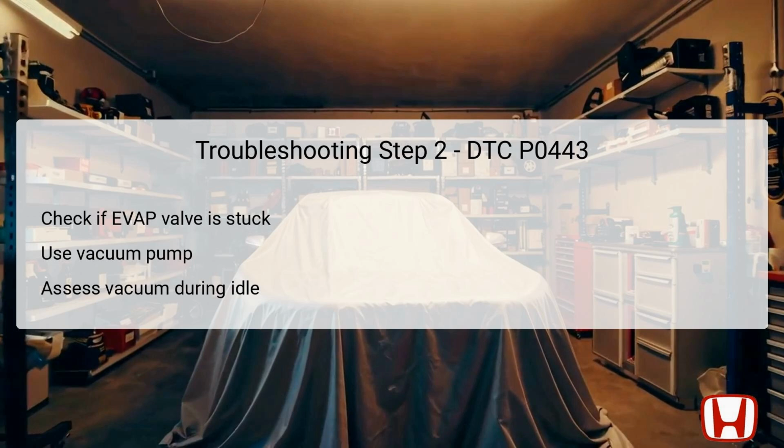Start the engine and let it idle. Check for the presence of vacuum. If vacuum exists, it indicates that the purge valve is stuck open, guiding you to the subsequent steps for diagnosis.